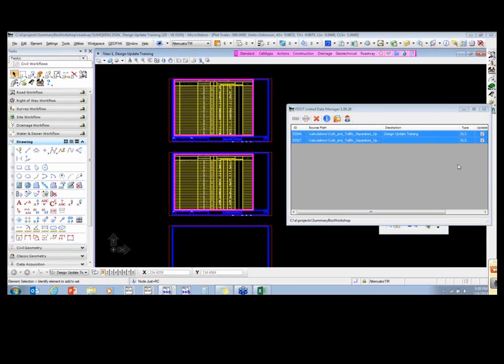That particular summary box does not have quantities associated with it per se, and the pay item along with the quantity goes on that temporary traffic control plan summary box. And both of those go on the summary of quantity sheets. They are not to go in the traffic control plans themselves. So that is different.